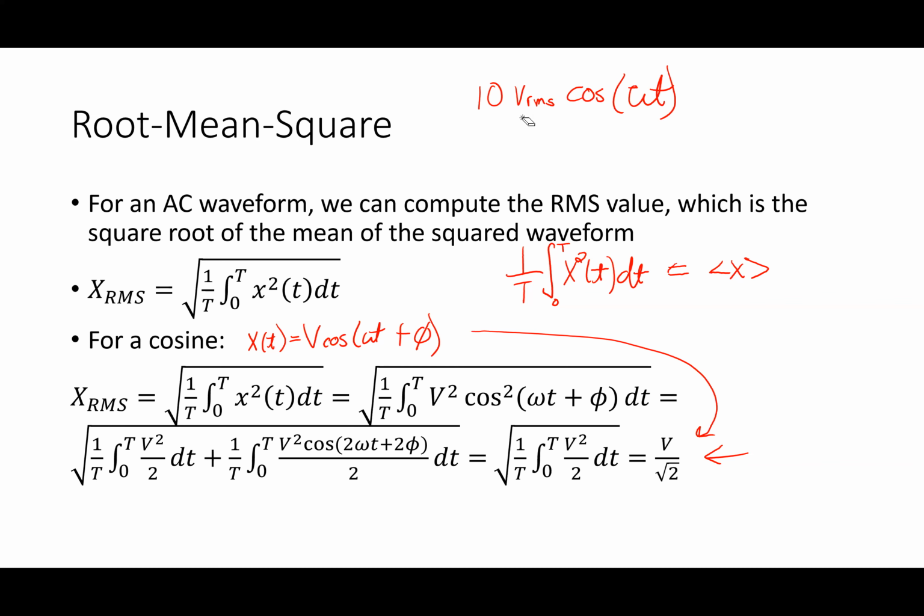So the peak value is the amplitude of the waveform. When you write the time domain expression, you don't write the RMS number times cosine. You write the peak value, the amplitude, times cosine. Now again, at this point in the delivery of this, it's like, well, why is he talking about this? Well, it does matter, for 2 reasons. Engineers always use it. Second reason, it is fundamentally what we use anytime we're talking about power.